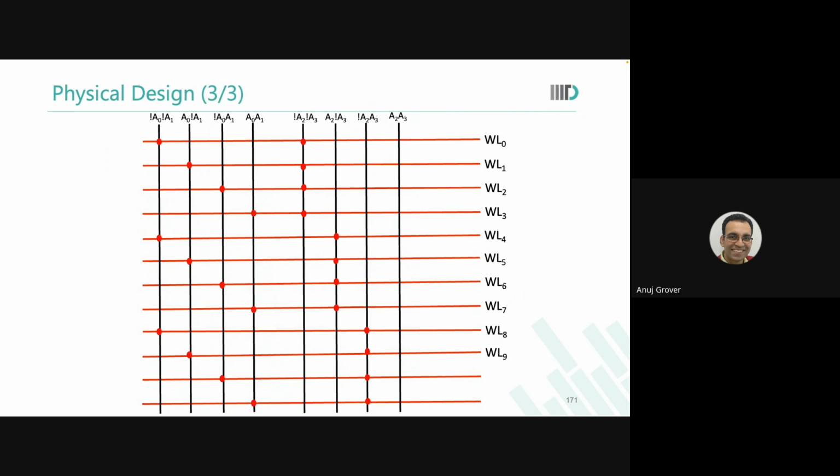And notice that near the boundary of the N well, this was your mask. So near the boundary of the N well, there is going to be a region where there are going to be more dopants. So what happens to this particular device, which is very close to the N well boundary? It has a different VT than the devices far away.